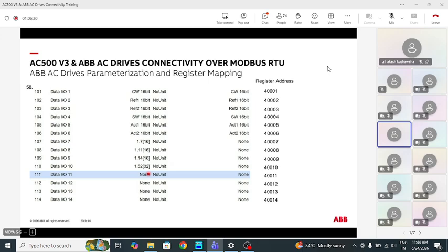since you're using ABB drives with the AC500 ABB PLC, you don't need to remember the register address. In case you're using any third-party PLC, and you want to give them the register address, simply remember 58101 is mapped to 40,001, 102 is mapped to 40,002 and so on. What you configure here, accordingly you can view it in holding register 40,000 number. I hope this is clear.